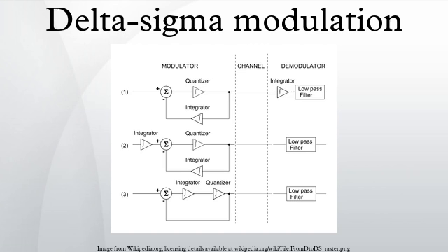Unfortunately the analysis for the transmitted pulse stream has, in many cases, been carried over, uncritically, to the ADC. It was indicated in section 2.2 analysis that the effect of constraining a pulse to only occur on clock boundaries is to introduce noise, that generated by waiting for the next clock boundary. This will have its most deleterious effect on the high-frequency components of a complex signal.